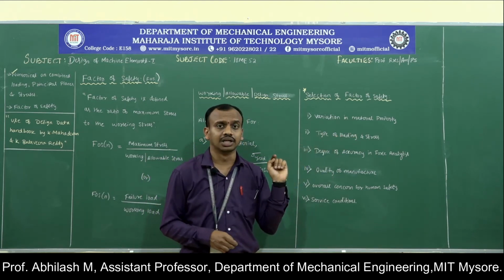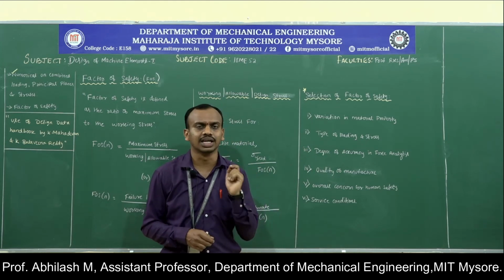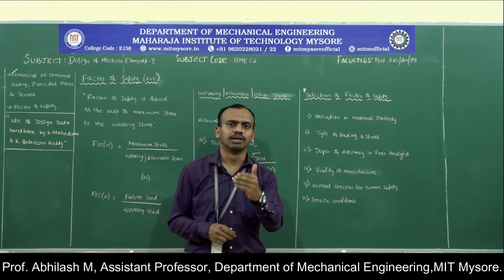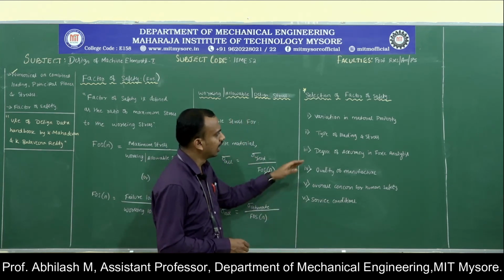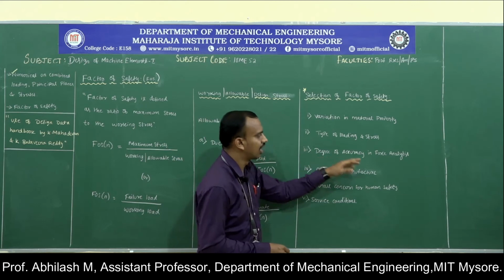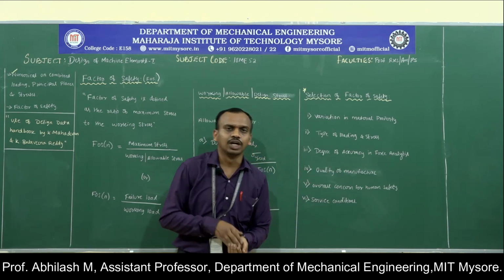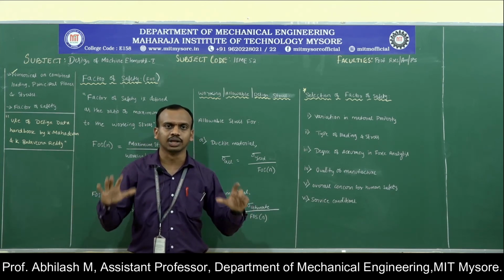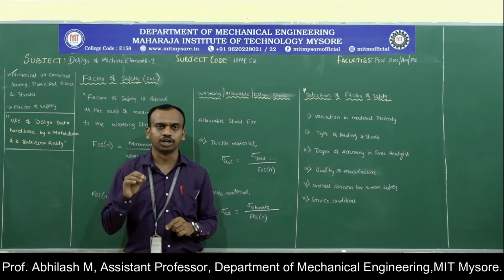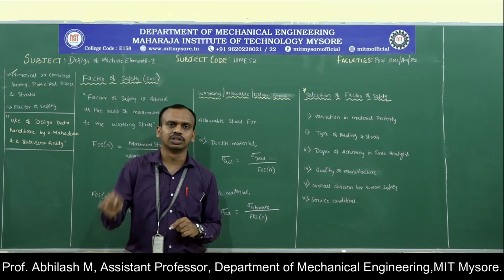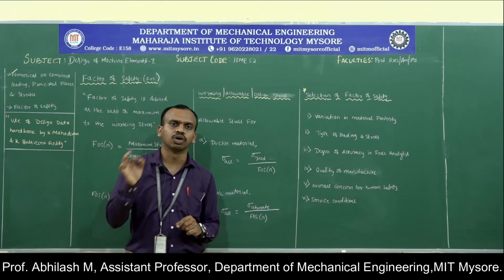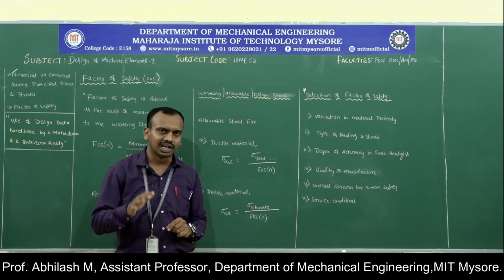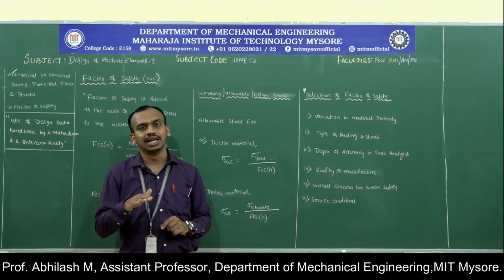Just in order to ensure the safety of that component, whenever there is an impact load acting on it, we should take a factor of safety value a little bit higher. Now, the next is based on the degree of accuracy in force analysis. While doing the design analysis, if you consider all the forces acting on the machine member, or if you have thoroughly analyzed all the forces acting on the machine member in both working condition and design state, then we can consider a factor of safety value lesser in nature.